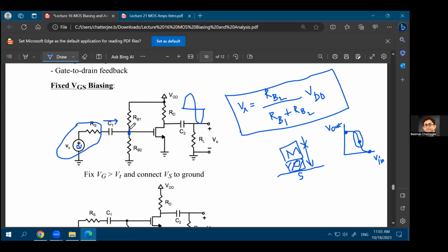And again, as you have learned, for very high frequencies, capacitance is a short. So for AC frequencies, assuming that this capacitance allows that AC signal to pass, you will see that the AC signal will be available at the input of the MOSFET. But the DC signal will not be available on the left-hand side. So in terms of DC, the left and right-hand side of the capacitance will be decoupled. But in terms of AC, they will be coupled, which means that the AC signal seen at the left and right-hand side will be the same for the capacitance, but the DC signal can be very different, and that's okay because you want to